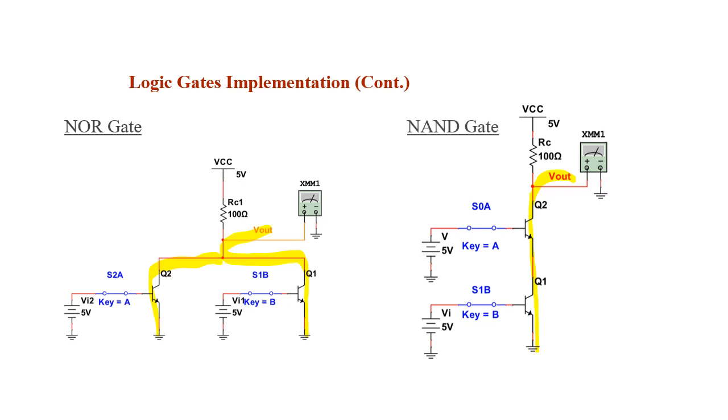So far, we've covered how to design the NAND gate, the NOR gate, and the inverter gate using BJTs. So understanding the basic digital logic skills, we can figure out how to design a 2-input OR gate with the use of a total of 3 BJTs, so that we can use the NOR gate output and then invert it using a BJT-based inverter, which we've explained how to do in the previous slide.